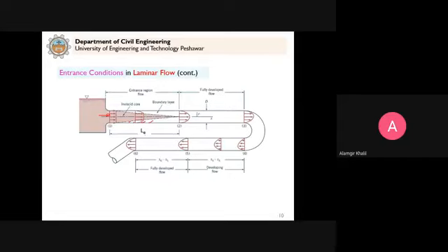And this boundary layer will increase in size from both sides due to symmetry, and then they will merge together. And this explains how the resistance is transferred towards the center of the pipe. So when they merge, what we get is a fully developed parabolic profile. And this is what we say is a fully developed flow.